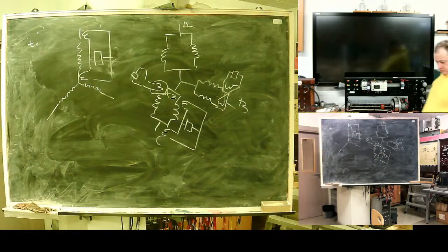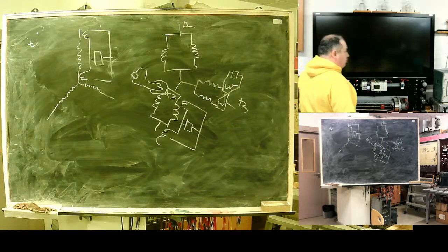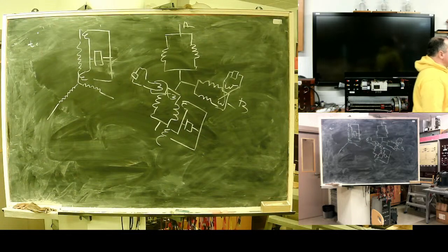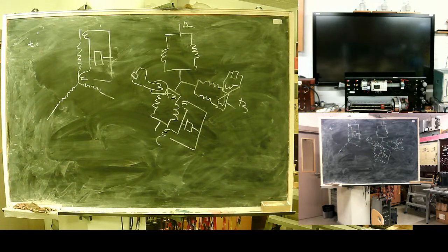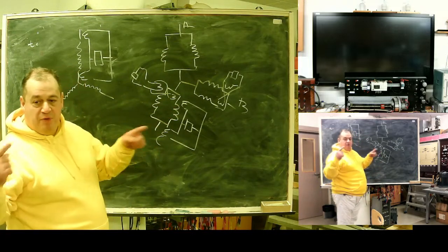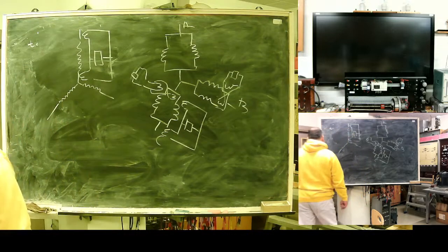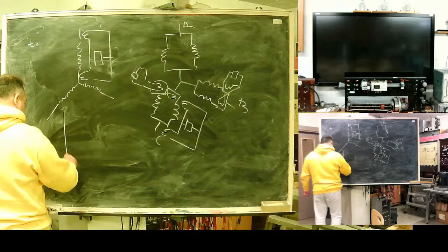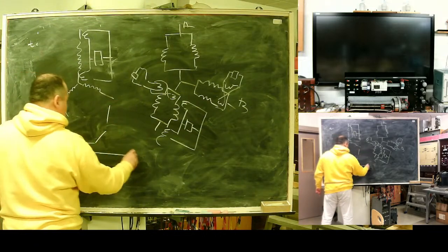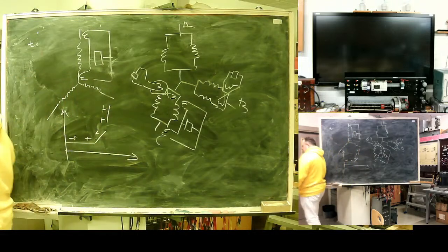High gigawatt class generators definitely will have multiple parallel branches in their stator winding. So each branch should be equipped with longitude differential protection, and current between branches should be compared. Works instantly. All characteristics are standard, approximation of current transformers error.